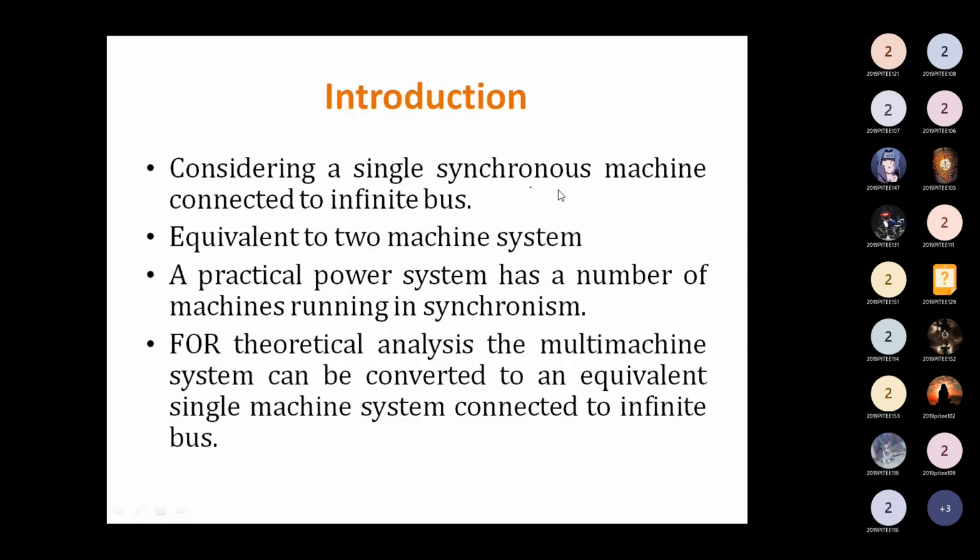A practical power system has a number of machines running in synchronism. We are going to deal with the theoretical case only. In practice, there are so many components connected in synchronism. Next, I just represented the theoretical analysis. The multi-machine system can be converted into an equivalent single machine system connected to an infinite bus. Theoretically, it is tedious to connect a number of buses, so I just consider a single bus system.